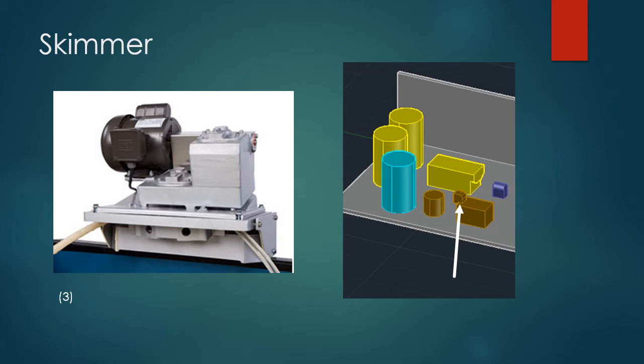The skimming tank is also where we will take the first steps towards taking care of water treatment that needs to be done, addressing the pH, BOD, and COD before we can release it down the municipal sewer. Once clean, the water will be stored in this blue tank for further testing and treatment, and also control of our discharge flow rate so we don't overwhelm the sewer system.